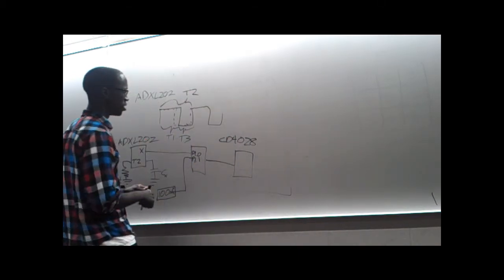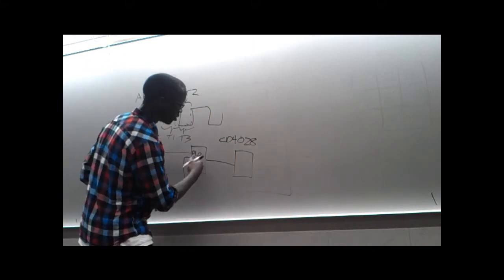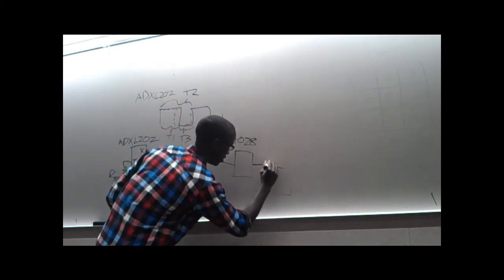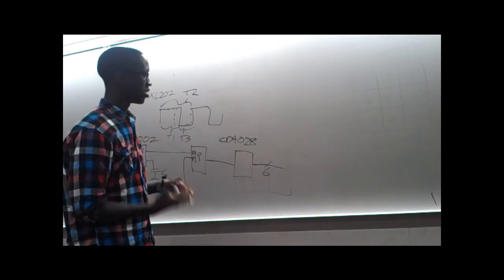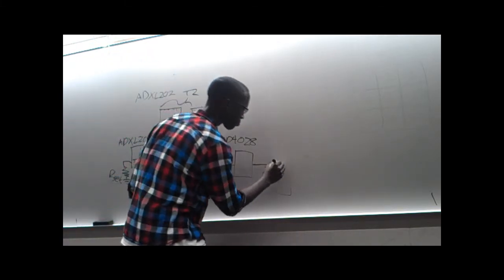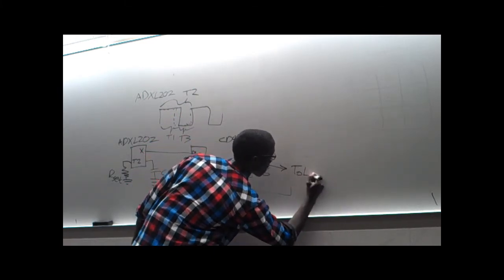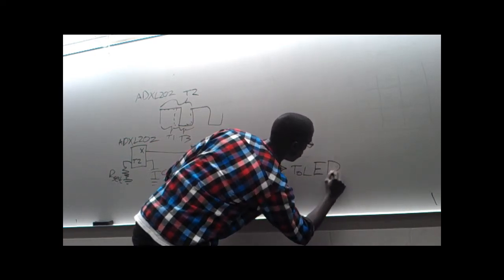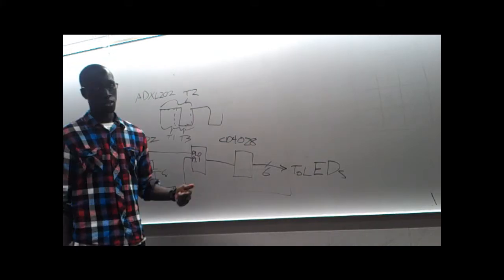In this case, I use the CD4028. And after it's output to the decoder/LED driver, it's output to the LEDs. And 6 LEDs were used to determine the intensity of tilt of the module. And then you have a really cool toy you can play with.